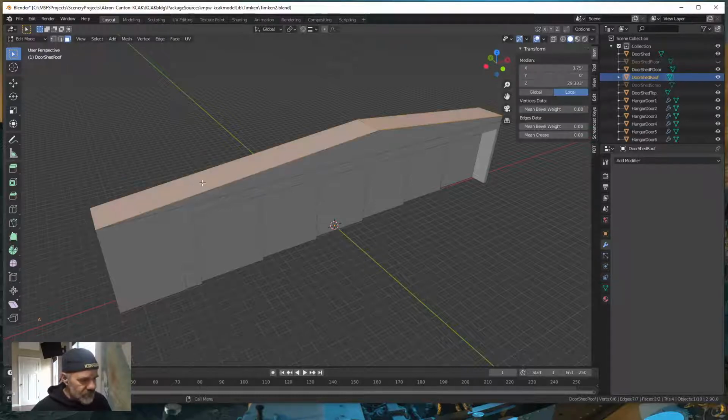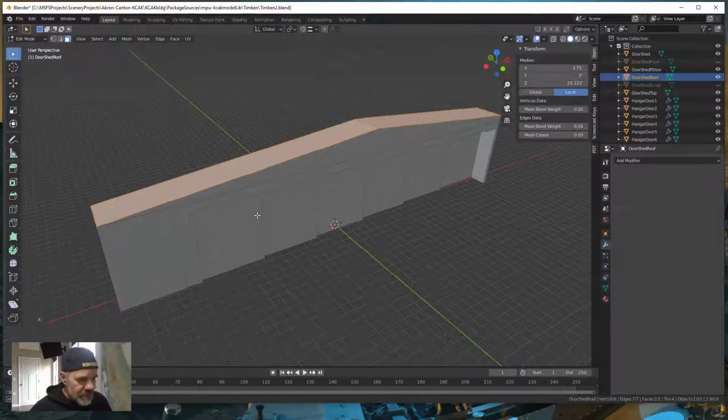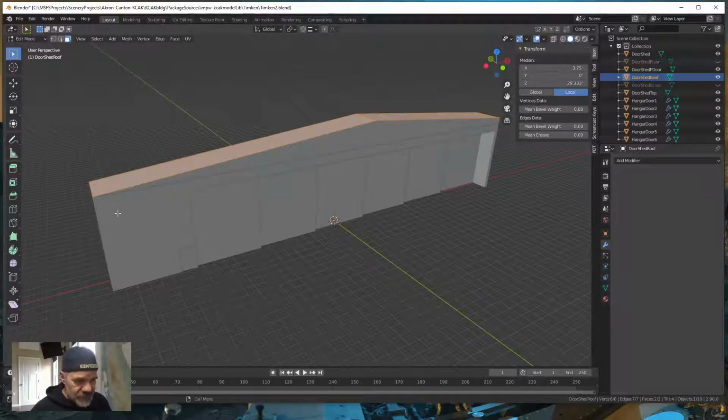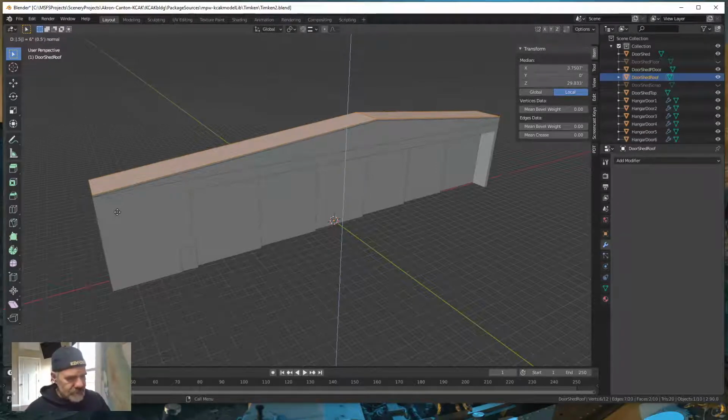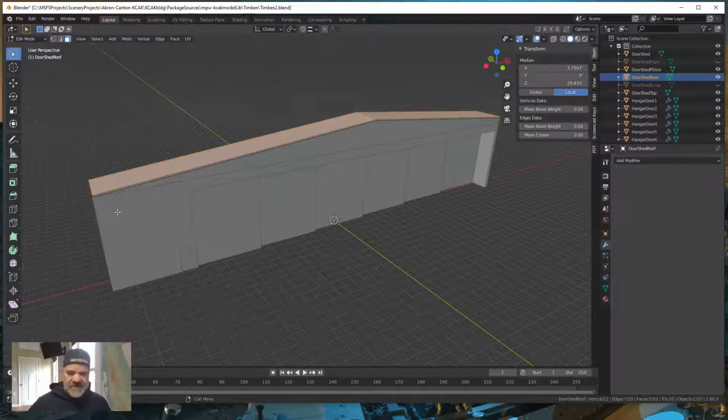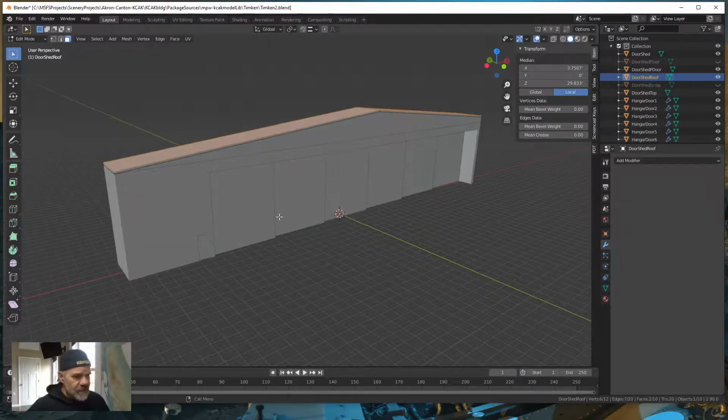you can hit A to select all the polygons, and we are going to extrude this in the Z direction 0.5 feet. Okay, so E, 0.5. You don't have to specify a distance because extrude knows which direction. It's either going to be positive or negative, in the direction that the face is. Okay, so now we have our roof